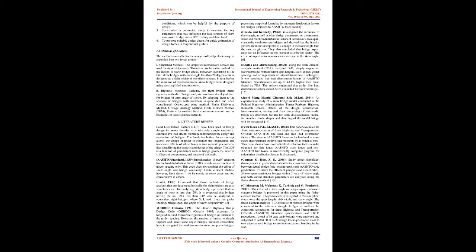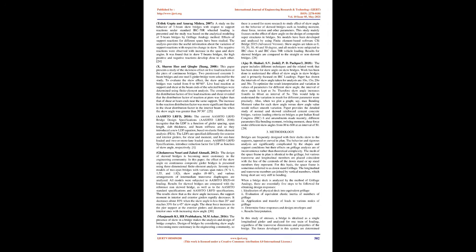In fact, before the advent of microcomputers, skew bridges were designed using the simplified methods only. 2. Rigorous methods. Basically for right bridges, many rigorous methods of bridge analysis have been developed, i.e., for bridges of zero angle of skew. Adapting them to the analysis of bridges with skewness is quite dull and often complicated. Orthotropic plate method, finite difference method, grillage analogy method, finite element method (FEM), finite strip method, and semi-continuum method are examples of such rigorous methods.